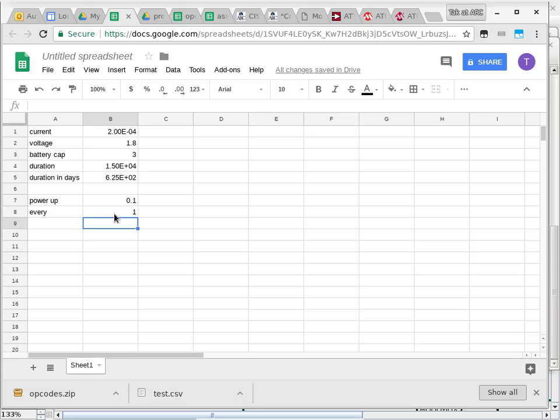Yep. Does it take extra power to turn it on to power? No, when you turn it back on again, it will only take the 25 or 200 microamps in this case. But it will ramp up too. So initially it's not going to consume 200 microamps. It's only when it gets up to full speed that it will be running at 200 microamps.